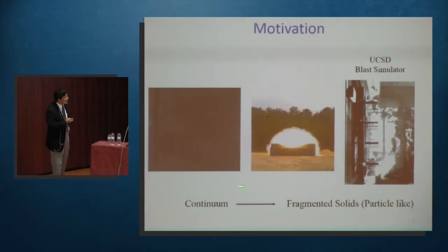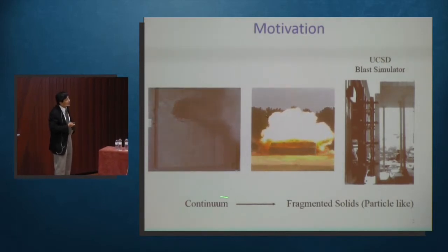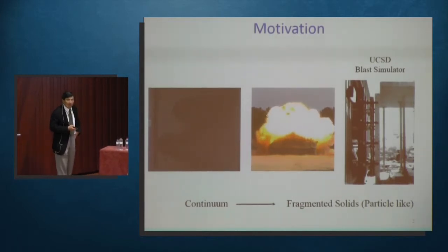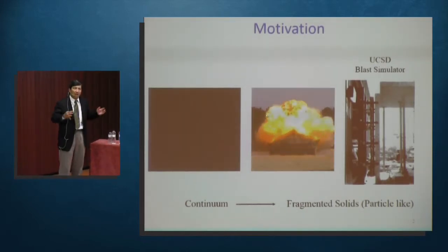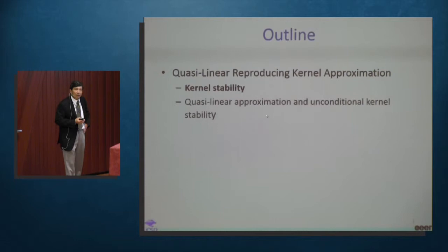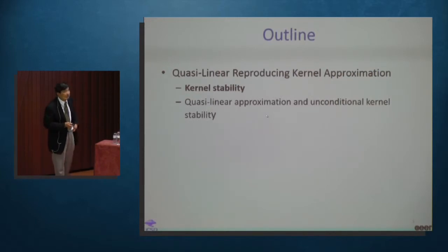Now, we have to deal with a problem that starts with a continuum and has to be accurate enough so that you capture all the key features that damage the material, all the way up to this level. Can I come up with a numerical method that can do this wide spectrum of deformation? And so we found that a mesh-free method is a good starting point for modeling continuum behavior of materials, even up to very large deformation. For example, plasticity, metal-forming. It actually works out very well compared to the conventional finite element method. But then when you get into particle-like motion, there are issues to deal with.